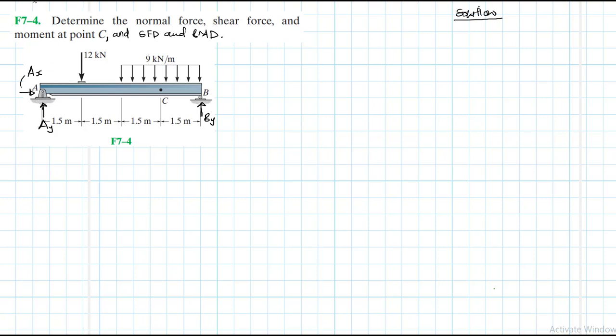All right, for the rectangular distributed load, for us to find the support reactions, we need to convert this to an equivalent force, and since this is rectangular in nature, we expect this rectangular load to be acting at the mid-center of the length of the rectangular load. And this one is going to be 1.5 on one end from the load and 1.5 to the other side.